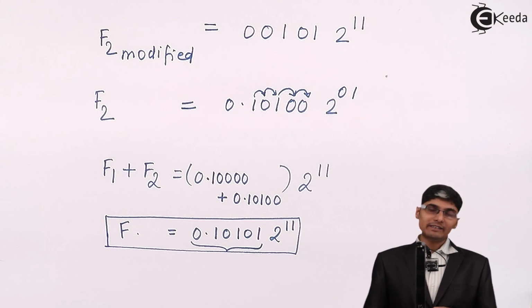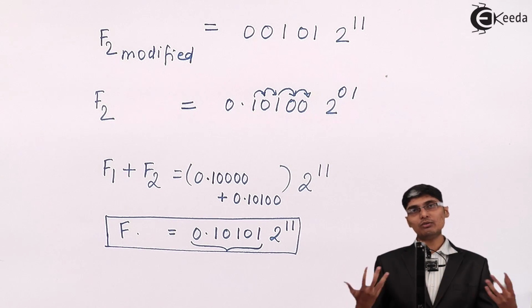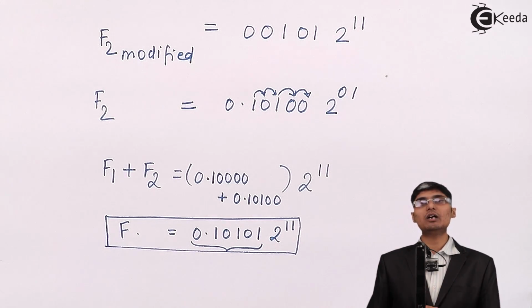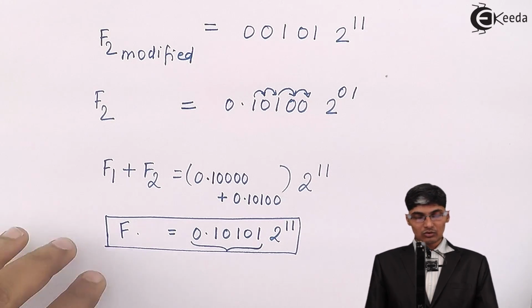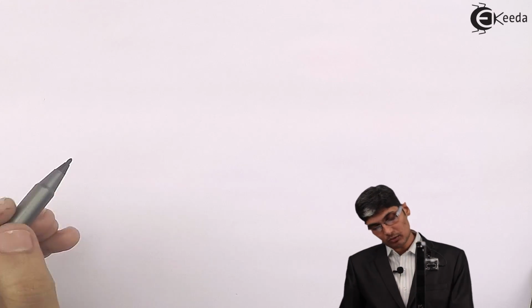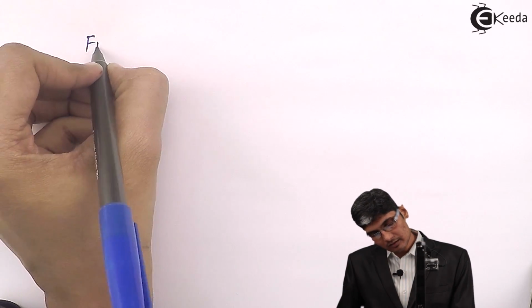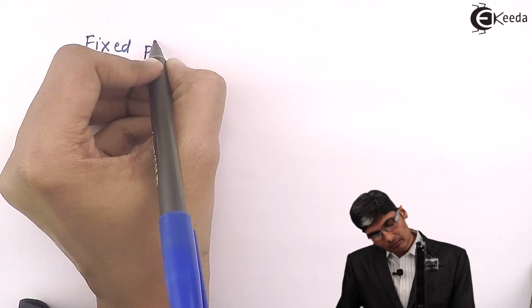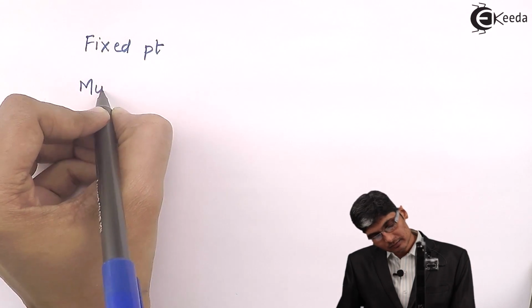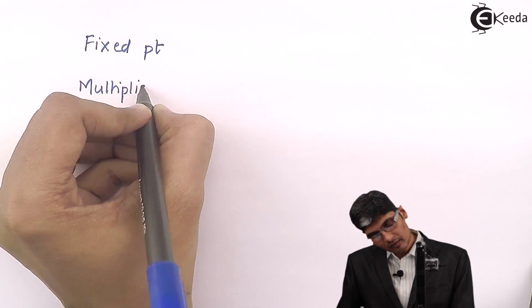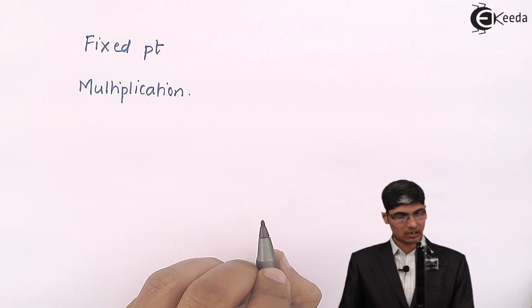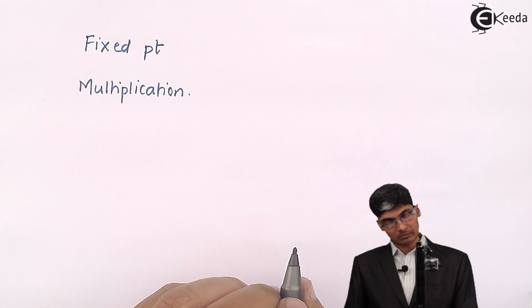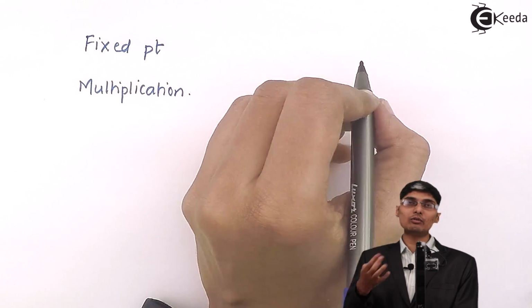Whereas the major problem of overflowing the bits or getting an increase in bits is of multiplication in fixed point. So if we just recollect the things, in fixed point the major problem will be with respect to multiplication. Of course, there will be some with respect to addition also, but the major problem that maximally occurs is multiplication, because 4 point will give you 8 point.